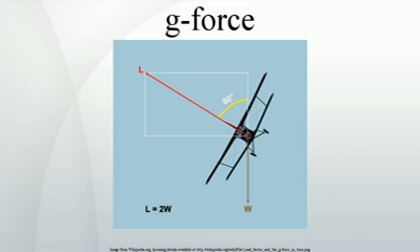Human tolerance of g-force. Human tolerances depend on the magnitude of the g-force, the length of time it is applied, the direction it acts, the location of application, and the posture of the body. The human body is flexible and deformable, particularly the softer tissues. A hard slap on the face may briefly impose hundreds of g locally but not produce any real damage. A constant 16 g for a minute, however, may be deadly.